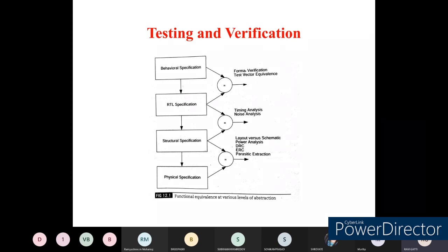synthesis. So means what, we go for error checking methodology. So if there is no error, or we have successfully run the syntax check, then we go for the RTL specifications. In the RTL specifications, we see how many logical elements we have used for the implementation of the behavioral specifications. Along with that we are going to see the timing constraints, whatever timing constraints we discussed in the earlier classes, the timing constraint specifications for the RTL schematics.